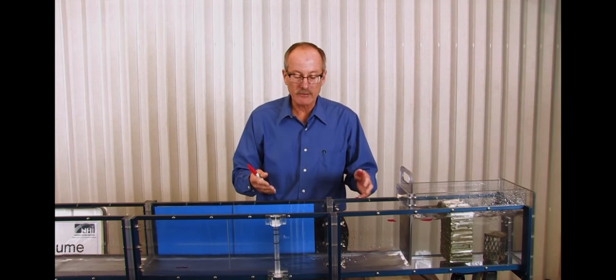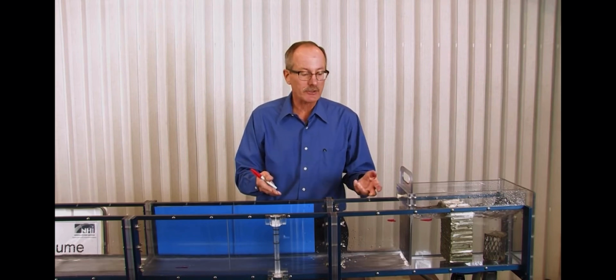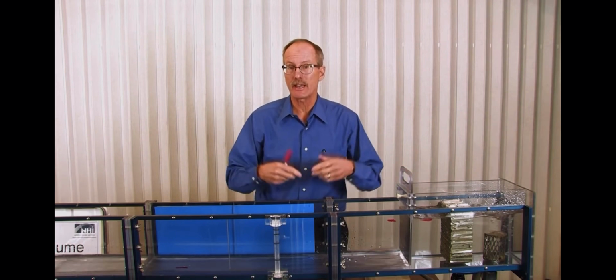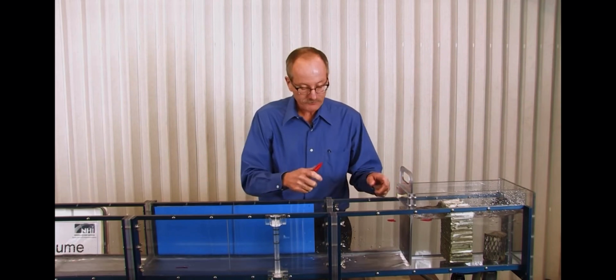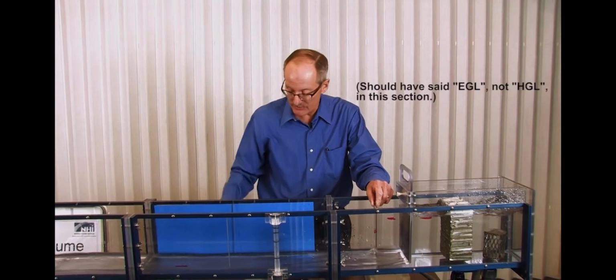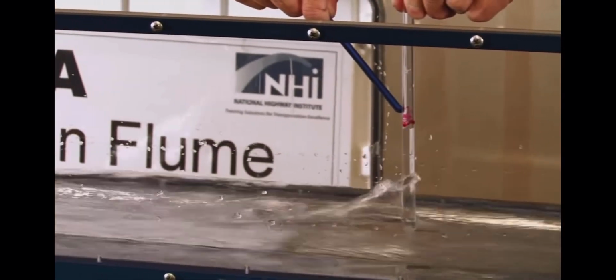The energy grade line is a sum of all the energy in the system, the potential energy plus the kinetic energy. The hydraulic grade line is below the energy grade line by the velocity head. Or another way to think about that, it's simply the sum of the elevation head and pressure head, the potential energy terms. So in my open channel here, we had a sloping HGL that you can actually visualize, which is what's kind of nice about doing the flume here. You can see what the HGL means.